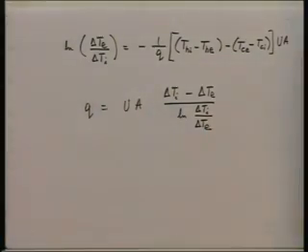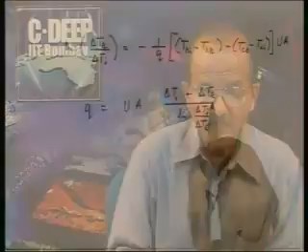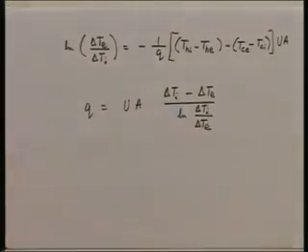Notice we have got the same equation as we got for parallel flow. In terms of symbols we have the same equation, but delta T i and delta T e mean different things in parallel flow and in counter flow. They are defined differently. That has to be always kept in mind.